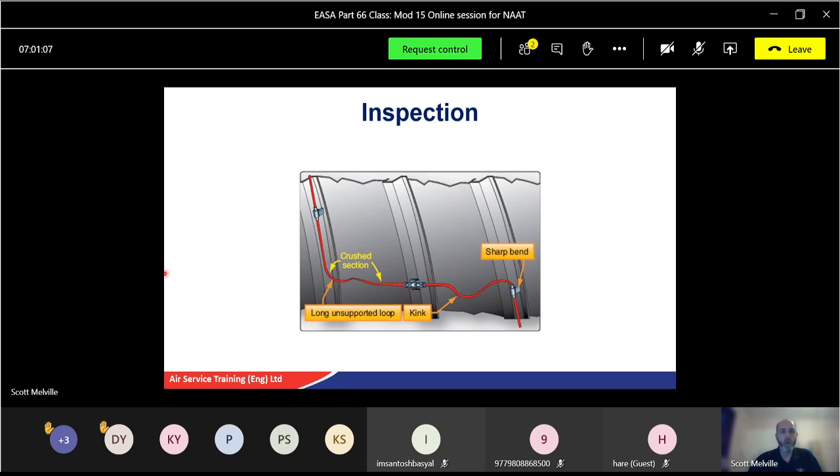You might have to do a connectivity test, a continuity or resistance check with the actual element off. So basically, if you're going to do one, you'll ground the electrodes and the outer sheath, the Inconel, and if you do positive to your electrode, especially in the Fenwell one, on the outside, there should be no contact. There should be no resistance there, or no circuit at least.